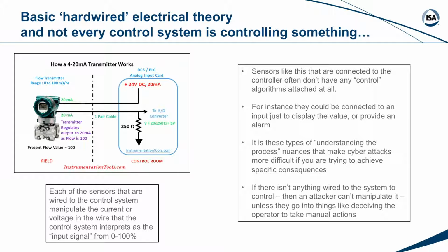In a 4 to 20 milliamp system, if the system has 0 in it, it means there's a fault or a break. You can also borrow some of the power in that 4 milliamps to power your instrument. So most of these instruments don't have separate power supplies, right? They glean the power off of that 4 milliamp signal going around in the circle.